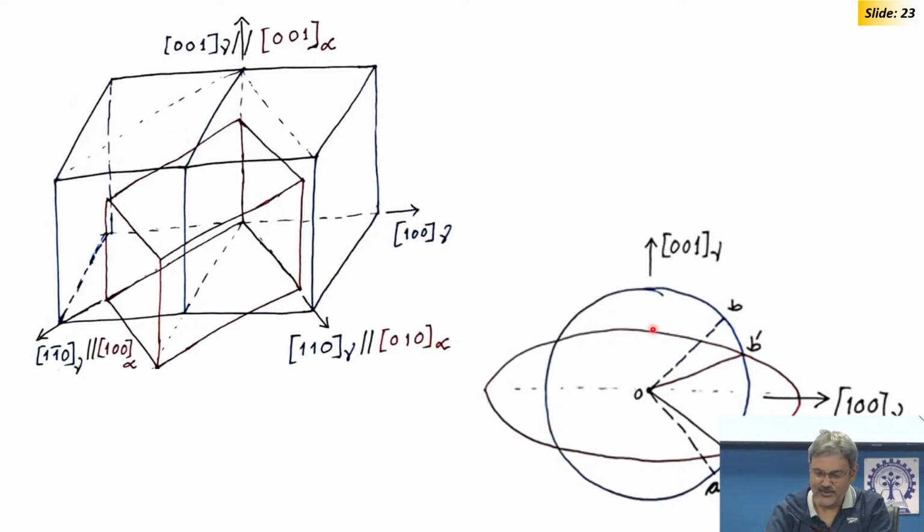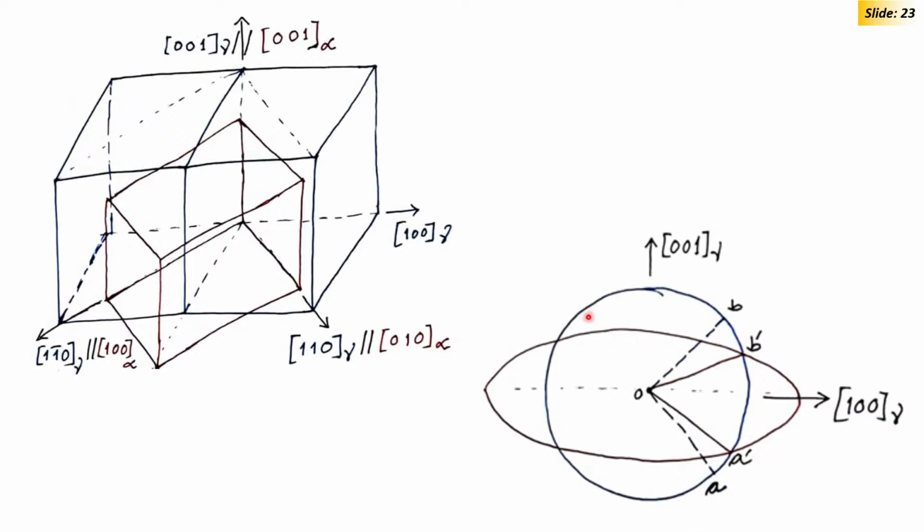You do this. So, the blue circle is austenite. I am drawing this blue box, suppose FCC in the form of blue circle, right. Now, what I am doing, I am applying a shear strain which deforms it. So, the red structure is its deformed version.